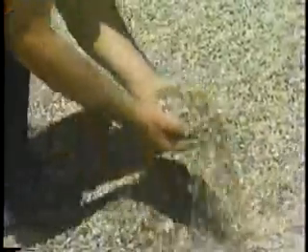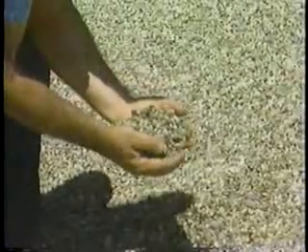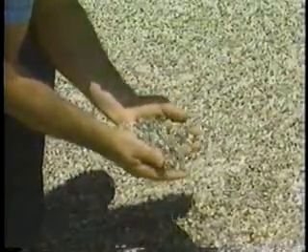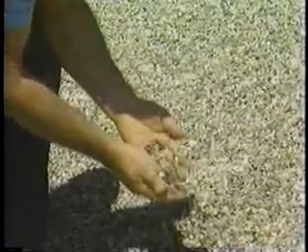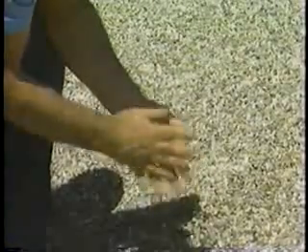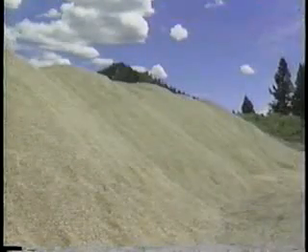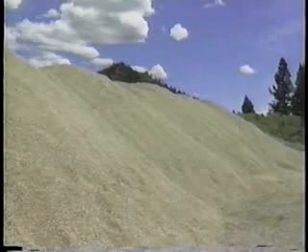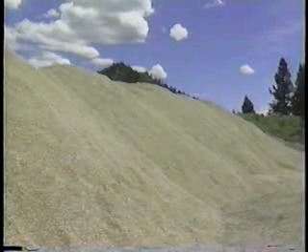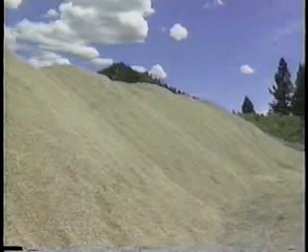The aggregate may be gravel, crushed stone, or slag. Individual particles should be cube-shaped and as nearly of one size as possible. Graded aggregate should not be used because the smaller material would immerse completely in the binder. It's important for the aggregate to be clean. If it's coated with dust or contains clay or silt, it won't bond properly with the asphalt.